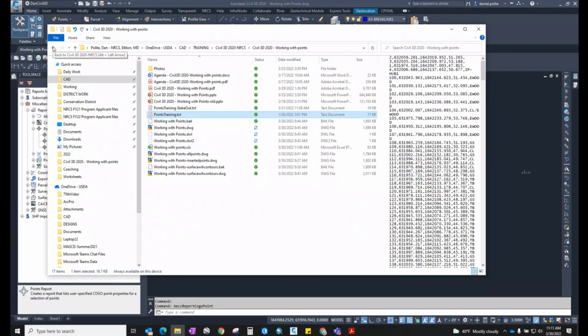Now, I guess on the raw file, you have to do that through the data collector, correct? Yeah, it's the same way. Well, at least on the Topcon Magnet, it's the same way. You just select your raw instead of points as your data. And then I've been doing RW5 files because those open up nicely into a text document, and that just works for us over here. And that's what I've been uploading with the zip file.